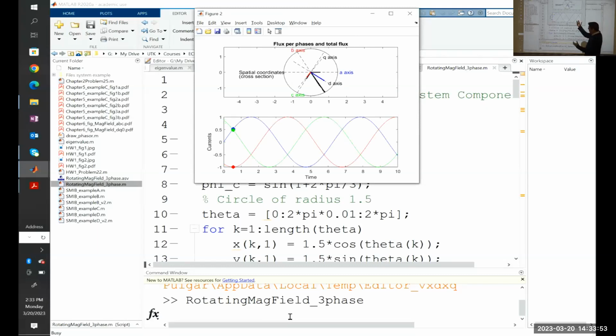So the situation is that because the rotor is rotating and the D and Q axes are stationary with respect to the rotor, the D and Q components do not change in time. And that is the mathematical simplification we achieve with this DQ0 transformation. So this is the first snapshot. And as you can see, for this point, this does not lead to any change in the components that we have in D and Q.